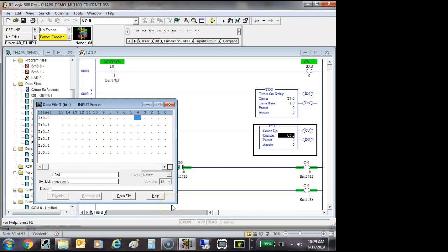Why is it there? Because it's a method of troubleshooting. Number one, it allows us to check a program with a PLC sitting over here by itself. So I don't even have it out in the plant yet, but I know input 1 is hooked up to this sensor and I want this to happen. So what I can do is I can bring this up and I can simulate these inputs without having any inputs wired. So you can actually check your programs out without even having the PLC wired up yet. So it's a really, really neat feature. Or we can see if this output is doing what it's supposed to without going through all the logic to generate the output. So it's a real valuable tool, but what I'm saying is you need to do what?